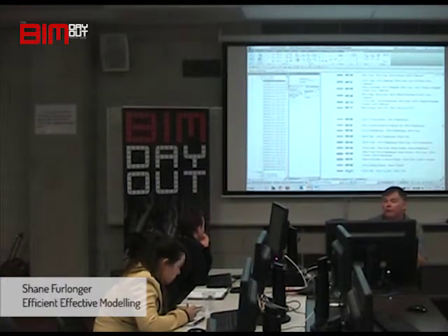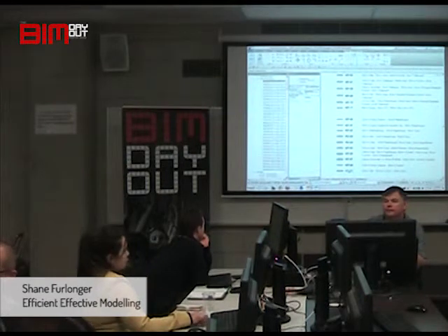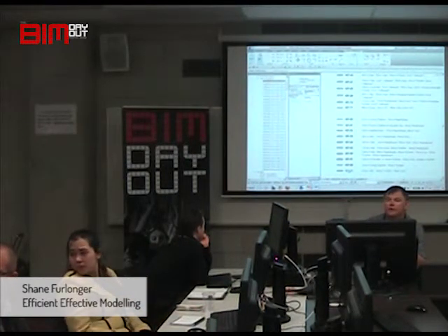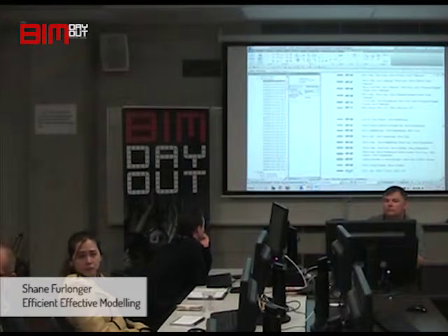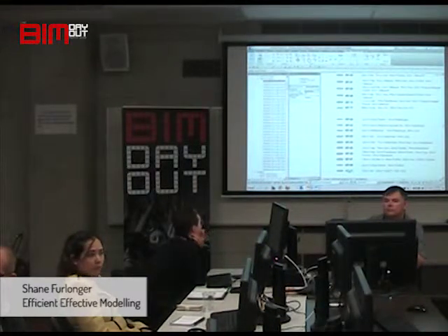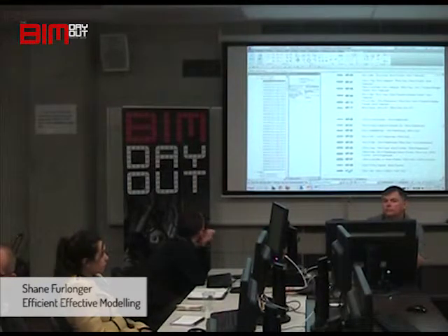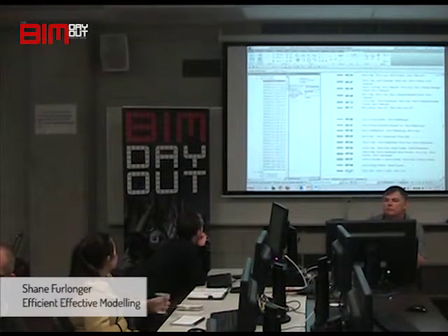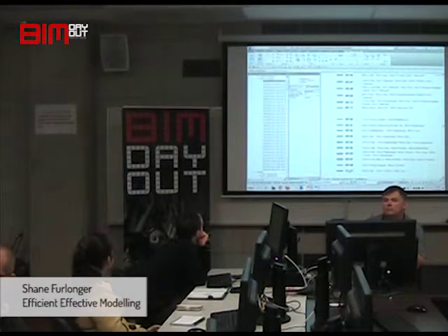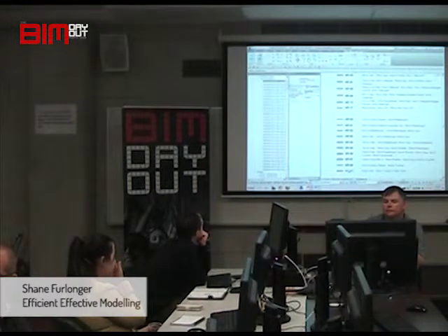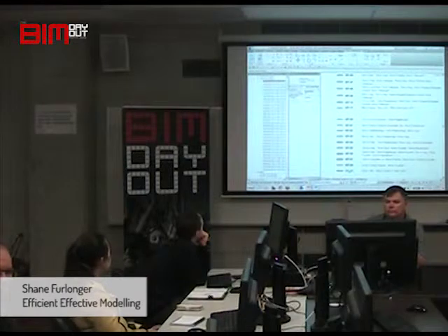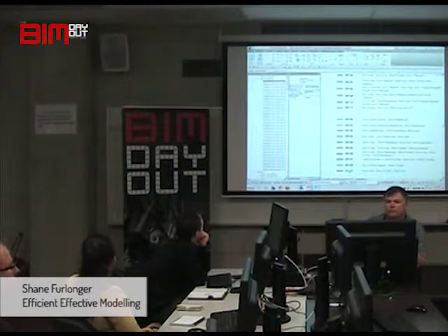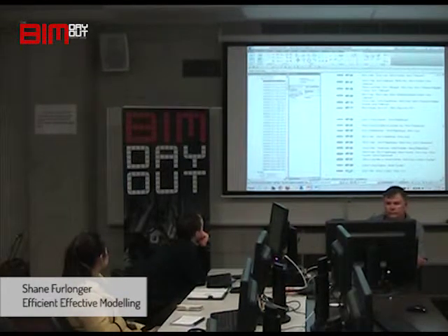Because it's dumb. The other thing I found is you can't actually dimension your walls, say your plasterboard and all that. You can dimension windows in a normal legend, but you can't dimension your walls. So say you actually want to pick up that there's two layers of plasterboard on one side of a 92 stud frame. You can write it, it can be in the description of the wall, but it can't physically be dimensioned. With this, it really exists. So you can actually dimension the elements of the wall within your legend that you're popping on your sheet or whatever.